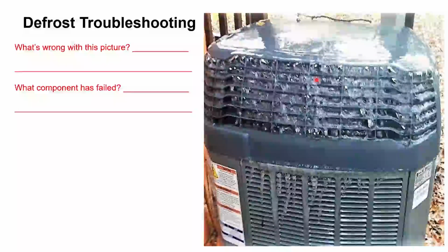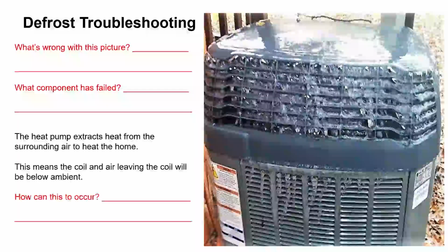And when we start looking at components of failure, well, what component failed? Well, it was the install that failed, right? We might end up killing a fan motor. That might be the complaint. We might end up with a complaint that the unit's not defrosting properly or is frozen up, and you come out, swap out the board and the sensors, and now all of a sudden you come back a few weeks later when we've got rain and freezing situations, and we've got a frozen unit again. And you can chase your tail. So make sure we're watching the overall install.